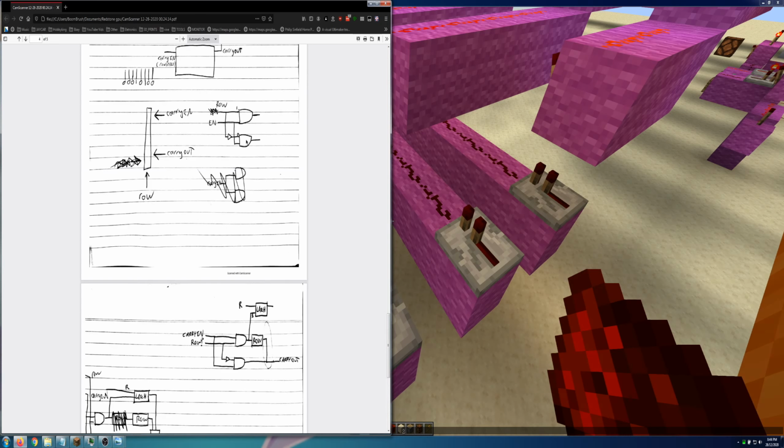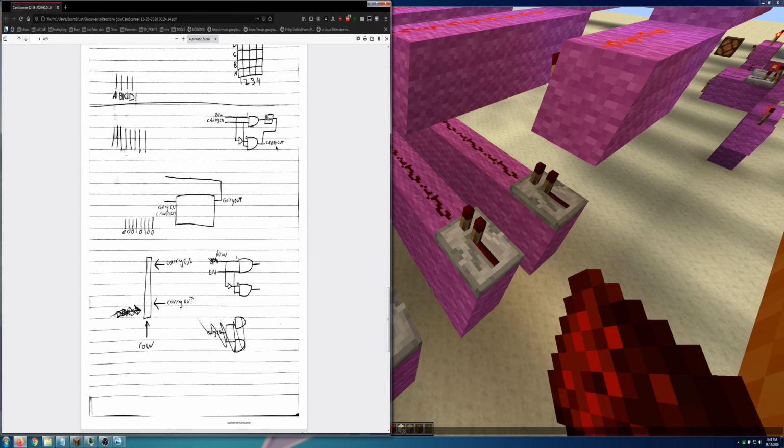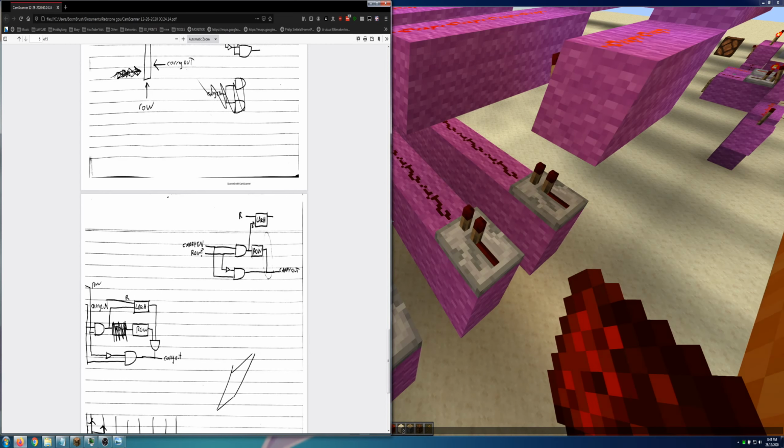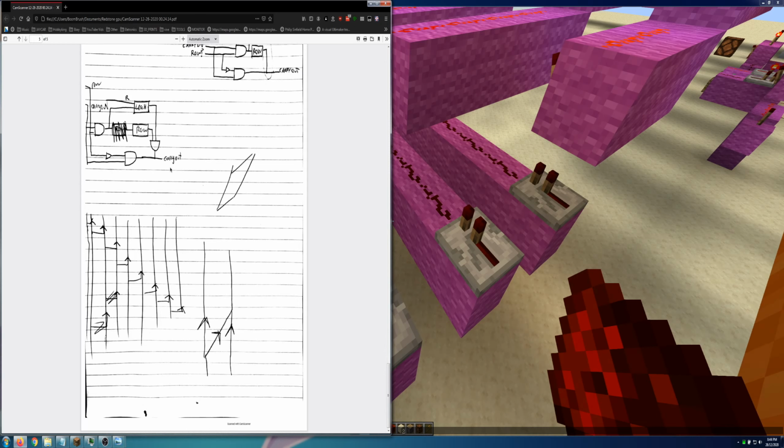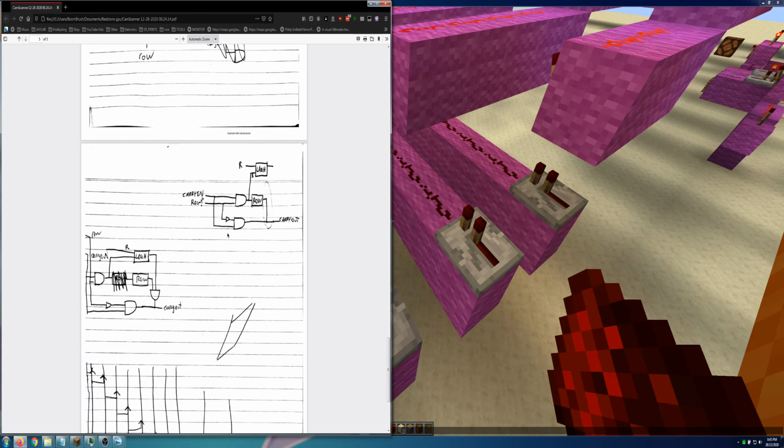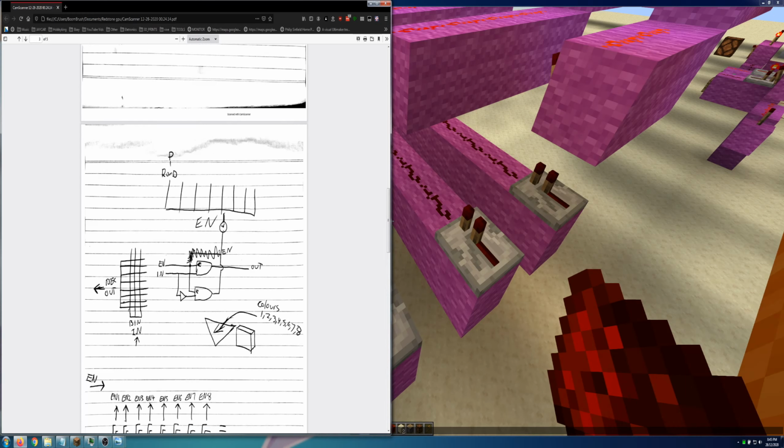Once that is complete, the last carry out signal from all of the columns will then go into the reset line of the latch. It will then act the exact same as the pixels and go to the next row. And if the row is not enabled, then it will just go all the way until the final end of the program. And here we have another example. After a set amount of time, it will go down as well.